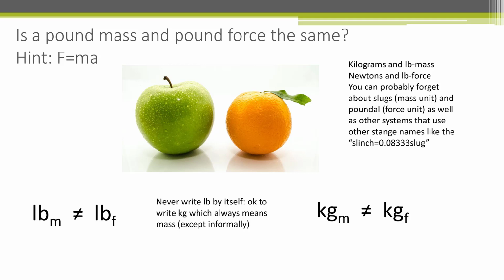In the SI system, the kilogram force unit is not used because it would cause the same confusion that we have with the USCS system by calling two different things by the same name. So in engineering work, do not use the kilogram force as it is a non-standard unit and is classified in the International System of Units as a unit that is not acceptable for use with SI. Instead, use the newtons. You will see the precise difference between weight, force, and mass as we go through the course.